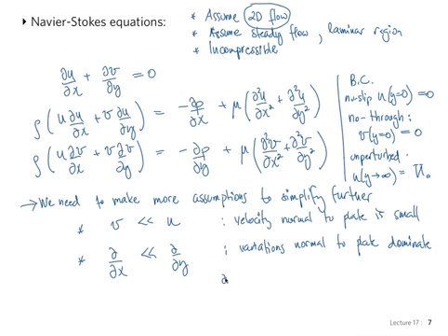So basically du dx is much, much smaller than du dy. The u velocity changes more in that direction by the effect of viscosity than it changes in the direction of the plate. And also for the second derivative we can do the same, or for the v. For example, v variation with respect to x is much smaller than v variation with respect to y.